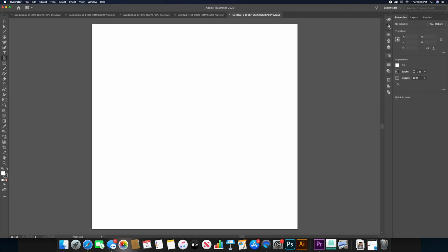Over on the right side navigation, there's a couple tools if you do not recognize the icons that we're going to be using today. The little club icon is the symbols icon. With the symbols icon, you can see a number of default symbols already placed in. We're going to be adding our own symbol today. Below this, we have the gradient tool, the stroke panel. The stroke panel will allow us to modify the thickness of the strokes. Transparency panel if you're looking to drop the opacity. But we're also definitely going to be using the Pathfinder tool.